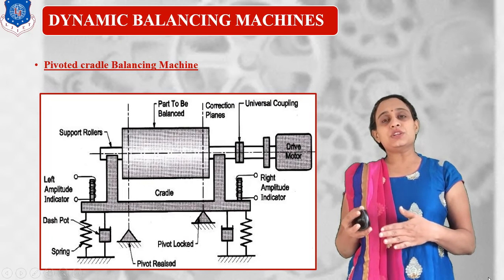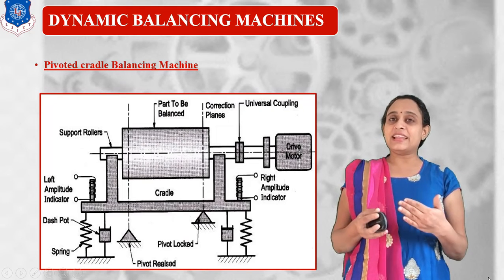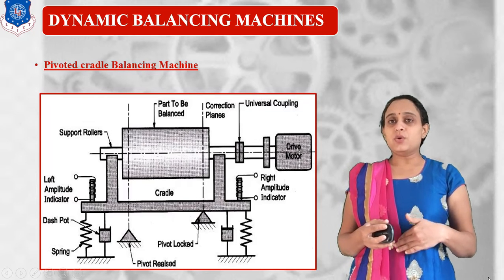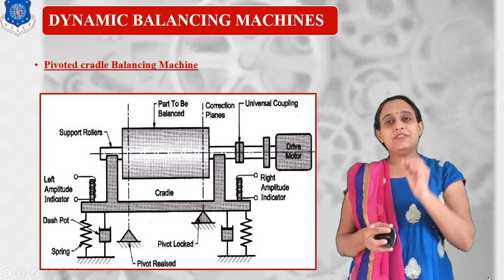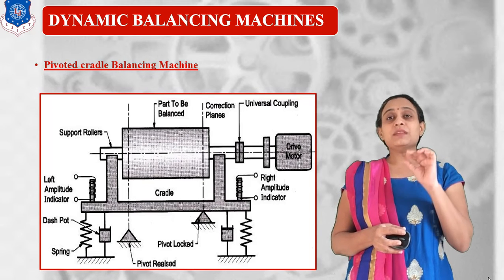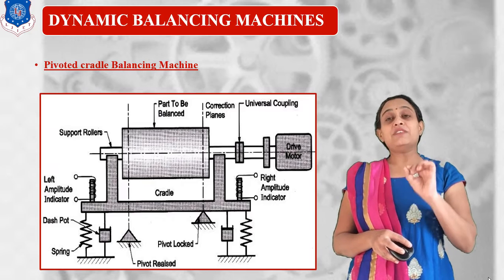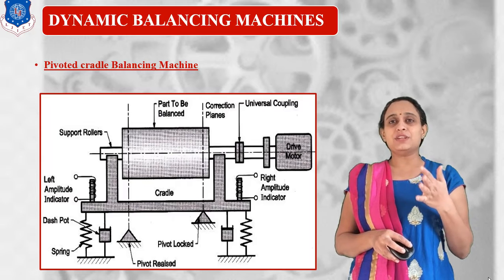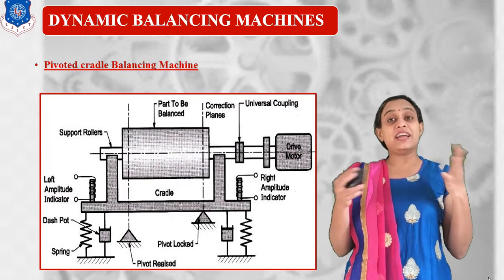By that calculation and with the help of the advanced system, we can directly measure whether mass should be added or removed. Now, if we need to add some mass, what do we have to do? We have to put that particular mass at a particular position in the x, y or z direction, and we need to fix it. It is not like a magnetic mass we put. We have to fix the mass by nut and bolt because they are giant wheels.